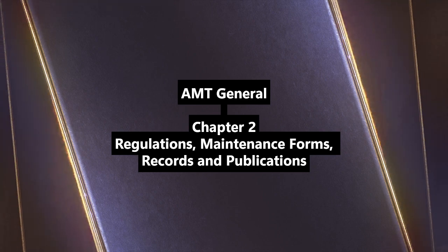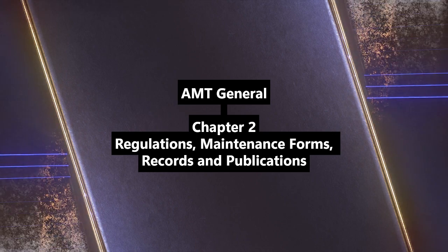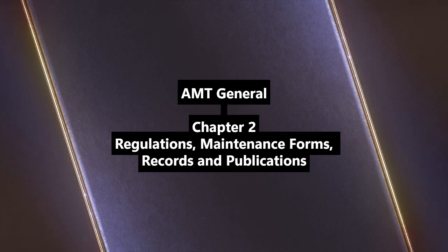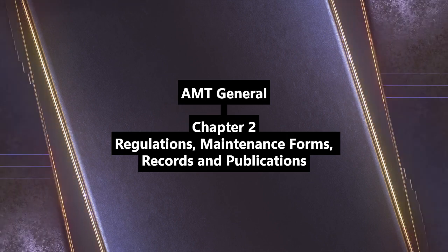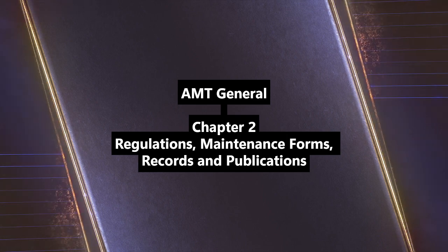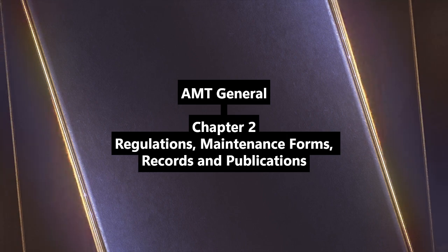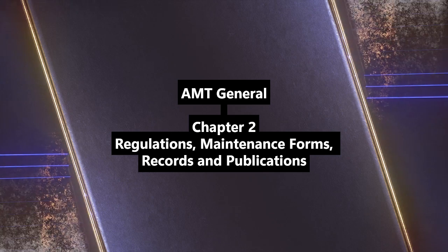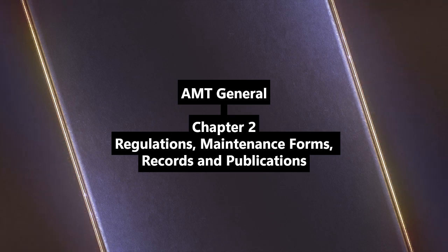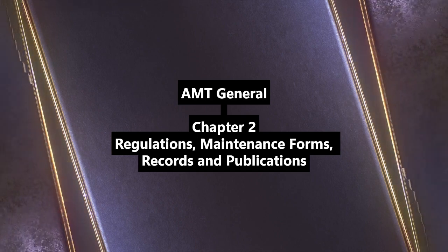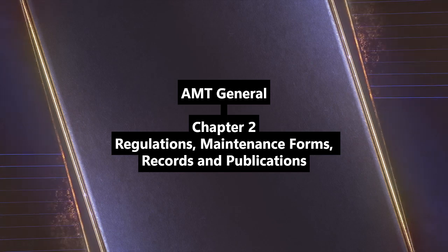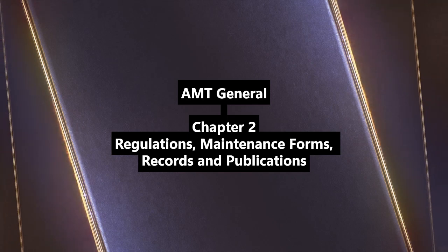Appendix E. Altimeter system test. The 411 test. Required every 24 months for IFR flight in controlled airspace, per 91.411. It tests the static system, altimeter, and altitude reporting equipment. Results go in the logs and on the altimeter. Who can do it? The manufacturer, an appropriately rated repair station, or an airframe mechanic, but they can only do the static system test. Mechanics can't calibrate instruments; that needs an instrument-rated repair station. Good to know. And TSO'd items? Considered tested at the manufacturer.